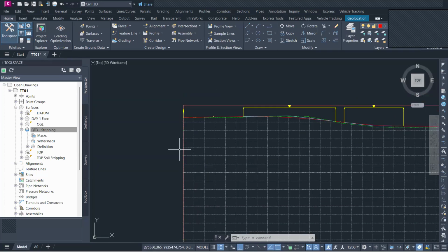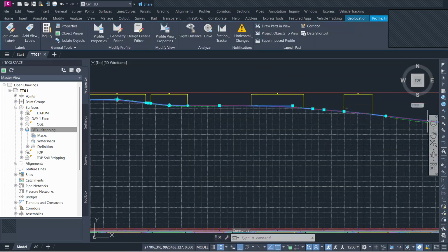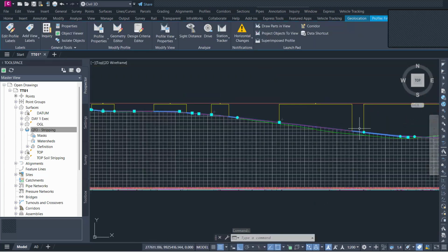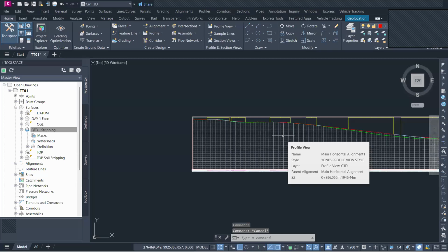When you're designing your road, you are following the OGL. The main guide is the OGL, reason being, you cannot design from unknown to unknown. So you always design from known to unknown. We already know the OGL, so it can guide us all the way to get the finished road level design.